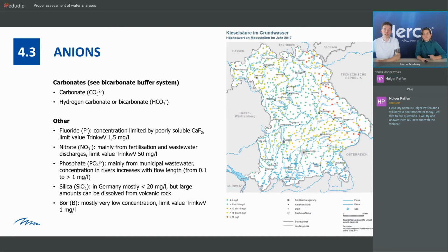On this slide, we see my favorite parameter. It's silica on the right side. So this is a really important parameter that gets forgotten very often, and it's really important for the electrodeionization systems, because some of it passes the RO and it really scales or fouls on the EDI stack and blocks it in the long term.